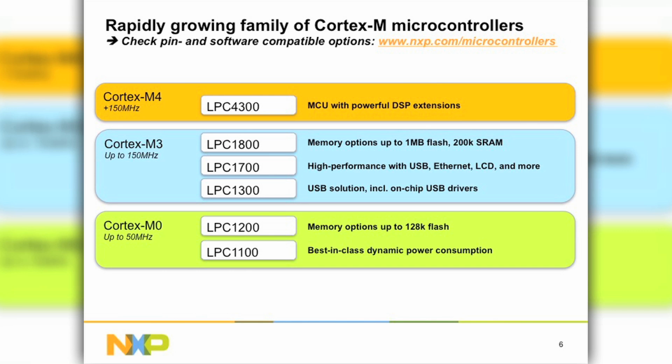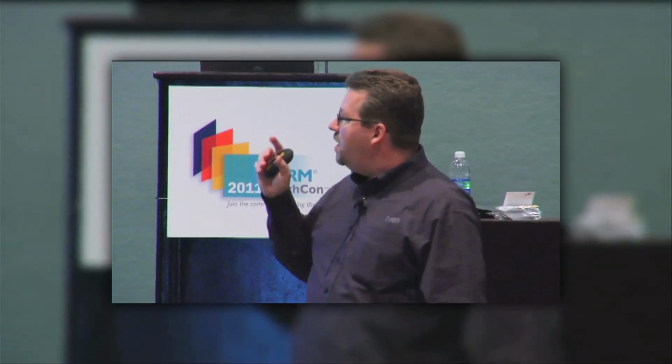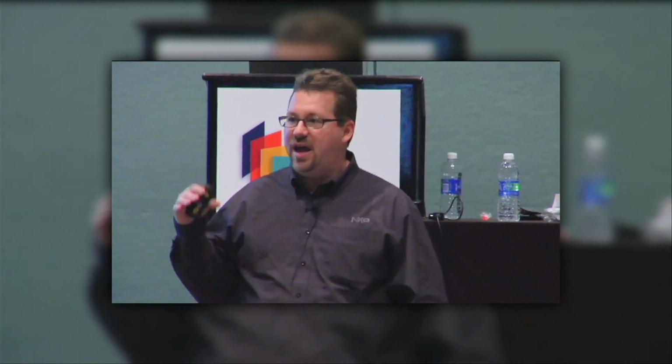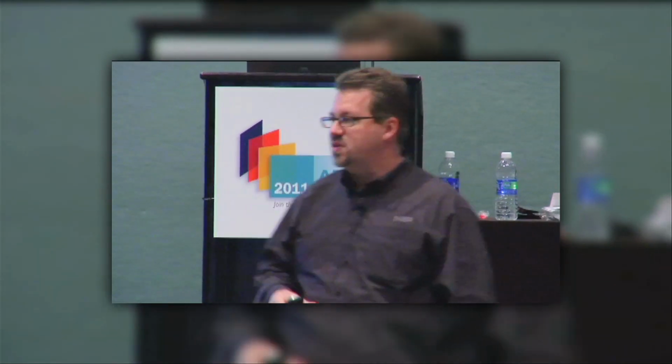All right, so M0, M3, what's the M4? Well, now there's the DSP space to look into. ARM said, let's take the M3 and add some DSP extensions. As it turns out, the M3 actually does DSP, and we'll see some benchmarks later. The question really is, with DSP, how fast can you go? What's the sampling bandwidth that you have to deal with? The difference between the M3 and the M4 we'll talk about in more detail, but effectively they've added single-cycle multiply accumulate instructions that allow you to do math functions like an FIR, an FFT, or an IIR much faster. And we'll talk about all those in more detail.